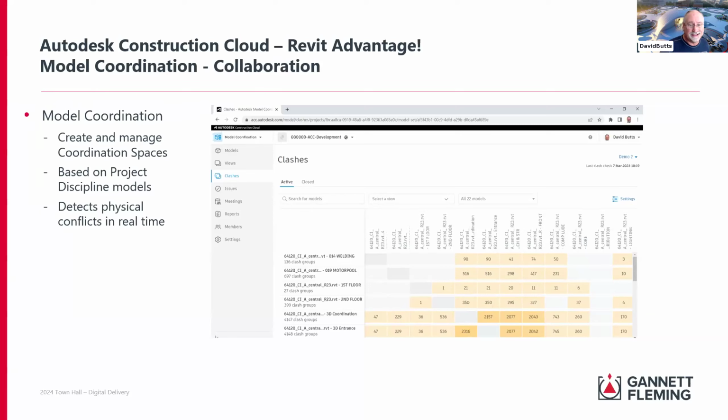A really cool feature about this is that you don't have to do anything. All you have to do is set up the space, get your models linked in, and then determine what types of clashes you want. You can see I actually went through this with one of my best architectural designers, a guy who used to be on my team and is now one of the senior project architects for the company. I said, let's take your project and make an example of it here. We said, all right, we want to compare the architectural model to the structural model and all the different files in here and different views within those files, and see where there are different clashes and different issues.